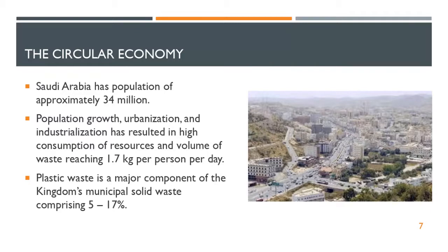Now you have the ability to change the composition of the petroleum fraction by using different petroleum sources and different distillation techniques. So you have considerable flexibility over the properties of the asphalt binder you make by choosing the right petroleum fraction in any one case. For hot regions like Saudi Arabia, you're looking for petroleum fractions that have high softening points, high softening temperatures, as opposed to in Canada, for example, where we are looking for asphalt binders that have different softening temperatures.